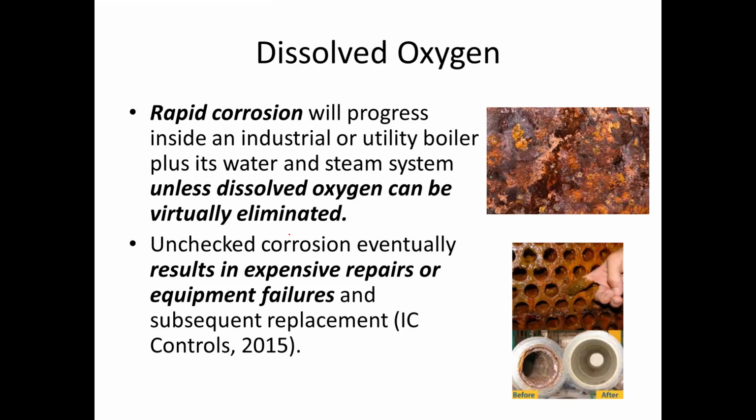There are different processes, and we discussed them last time, to remove dissolved oxygen. One of them is the oxygen scavenger with the use of hydrazine, and other oxygen scavengers like sodium sulfite. However, hydrazine is no longer preferred. Other than chemical treatment, we also do mechanical deaeration, wherein we let the feed water pass through a hot surface so that dissolved gases like oxygen or carbon dioxide will evaporate and will not contaminate our boiler feed water that we supply.